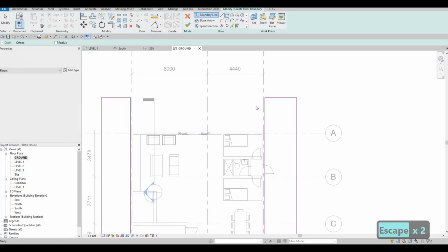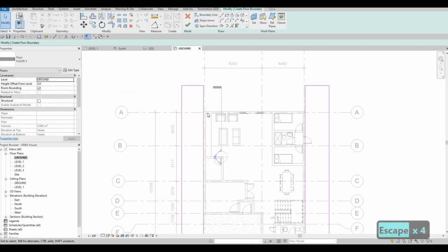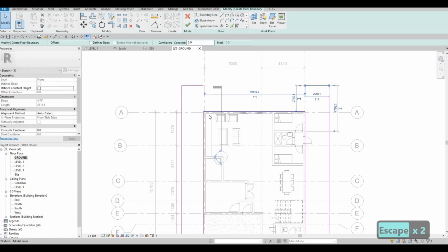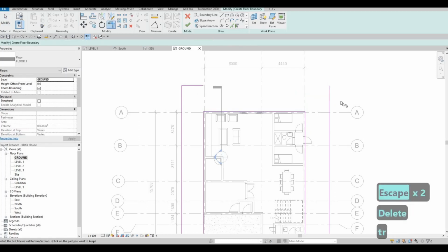So it's easier to do for now, and then edit will be faster. So here I'm going to pick line to make it fast. We could trim this, TR, trim this, just delete one of this, and then TR again to make it fast.